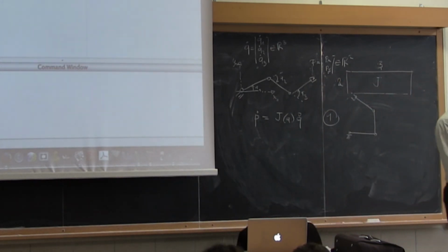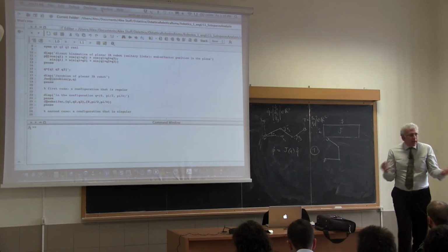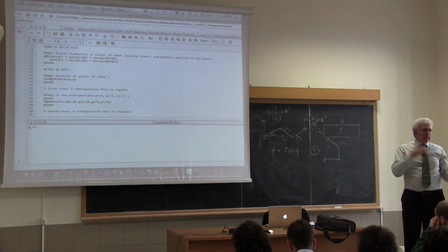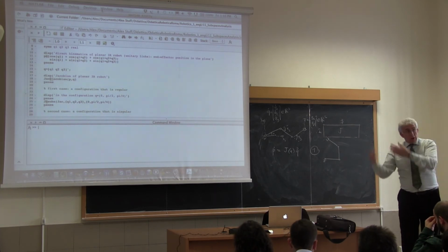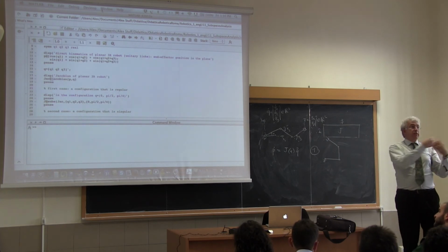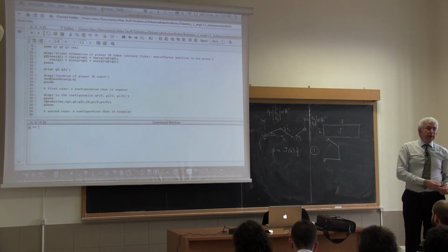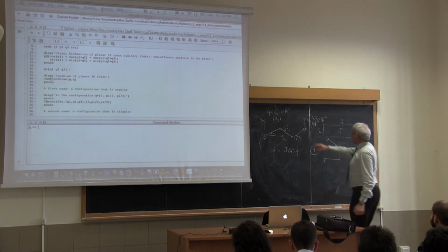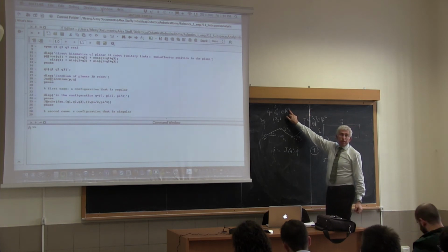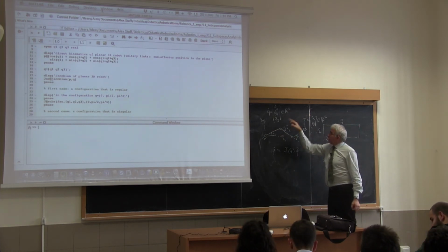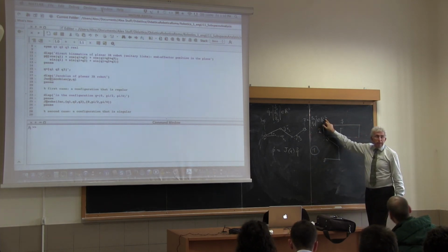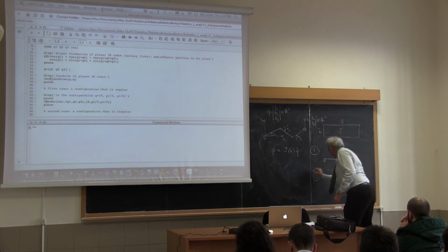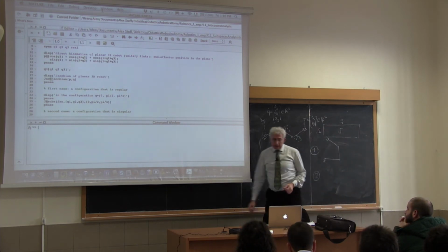And we will see in this configuration what happens to the Jacobian. Is it full rank? What is its null space, its range space, the Jacobian transpose null space, the Jacobian transpose range space, and the dimensions? Do the sums give the proper dimension, 3 if we are working in the joint space, or 2 if we are working in the task space? And then we will change to a new configuration. But let's start as follows.